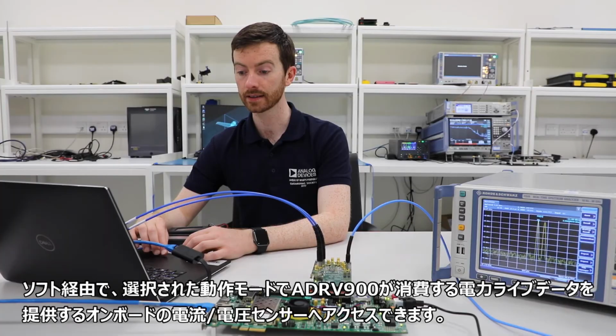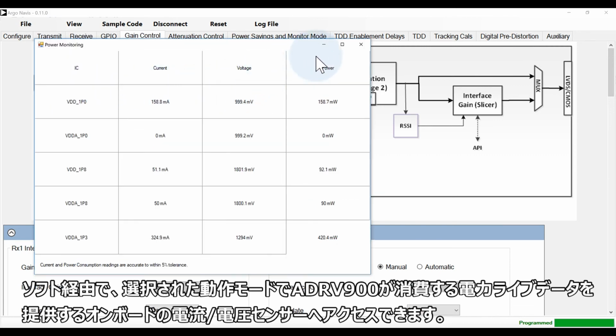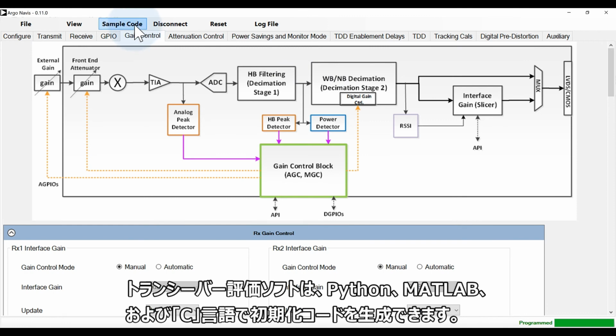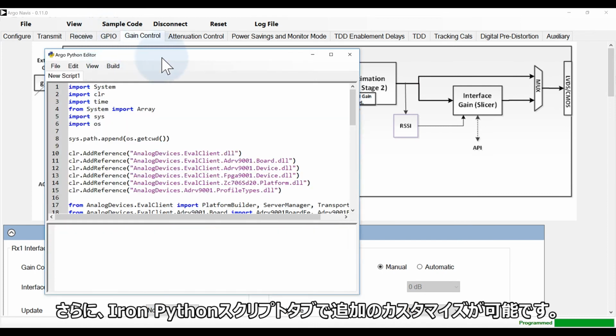Software provides access to onboard current and voltage sensors that provide live data on power being consumed by the ADRV9002 in the selected mode of operation. The transceiver evaluation software can generate initialization code in Python, MATLAB, and C languages. Generated code will reflect the exact state of the ADRV9002. Further, an IronPython scripting tab is available for additional customization.